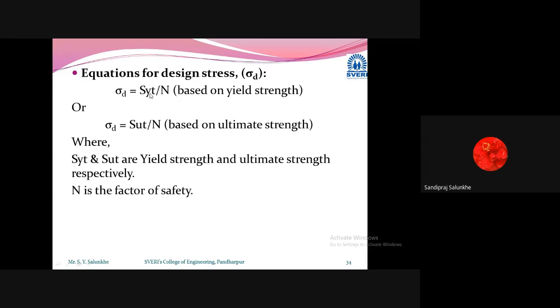In the elastic limit also they are elongating. But when you remove that load, they regain their original size and shape, and that is allowed. But if it goes to the plastic stage, then it is considered a failure. That is not the case for brittle materials. In brittle materials, we do not find that plastic, elongation stage.